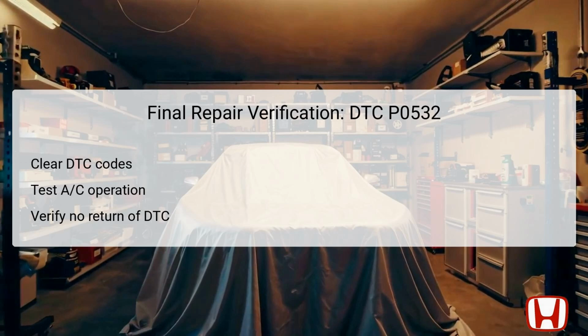Following this, you should test the operation of the AC system to ensure that it functions correctly and provides adequate cooling performance. Observe the system to ensure that it operates smoothly and monitor the AC pressure sensor's readings. Finally, you must verify that the DTC does not return upon rescanning with the HDS tool. This comprehensive approach to repair and verification helps ensure the vehicle is operating correctly and confirms that the troubleshooting steps were effective.